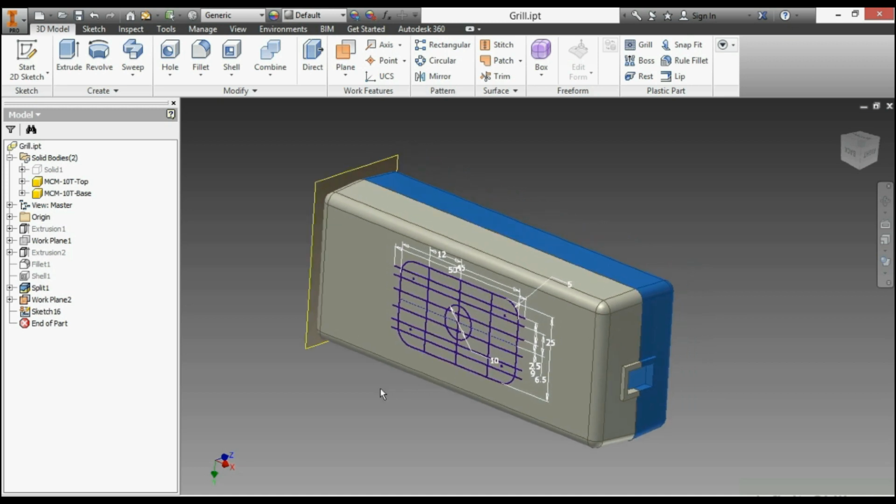And what you need to know about this particular sketch is the idea of a boundary, an island, ribs, and spars. Now the boundary is this overlying shape along the outside. You must have this for the grill command. I also have an island that I'm going to create on the inside, the circular shape. I have ribs that go across the sides here, 1, 2, 3, 4, 5, 6. Now they don't have to touch the boundary, they can extend beyond it. They don't have to extend beyond it. I just am showing that for the methodology where you could do that.